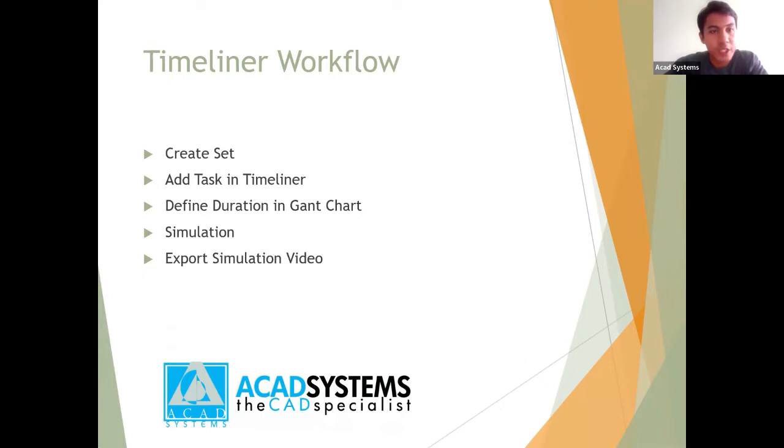Before we jump into Navisworks, this is the overall Timeliner workflow. We have the model in Navisworks, and then we create sets, add tasks in Timeliner, define the duration in the Gantt chart, run the simulation, and lastly export the simulation video. So without further ado, let's go to Navisworks.